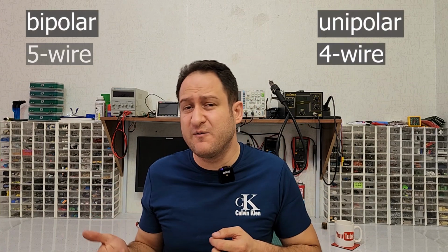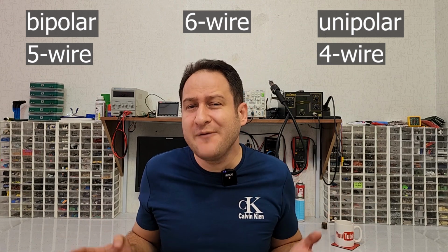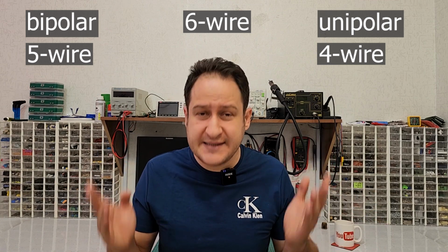The first thing to discuss is the stepper motor type. You may have heard of many stepper motor categories: unipolar, bipolar, 4-wire, 5-wire, 6-wire stepper motors. I have to tell you that all of these are the same. Categorizing stepper motors into groups like unipolar or bipolar is done mostly based on how to drive them, not the stepper motor itself or its inner structure or its nature. Also, categorizing stepper motors by their wire count is not correct. You may ask how a 4-wire stepper motor can be the same as a 6-wire stepper motor. Good question, I'm gonna explain.